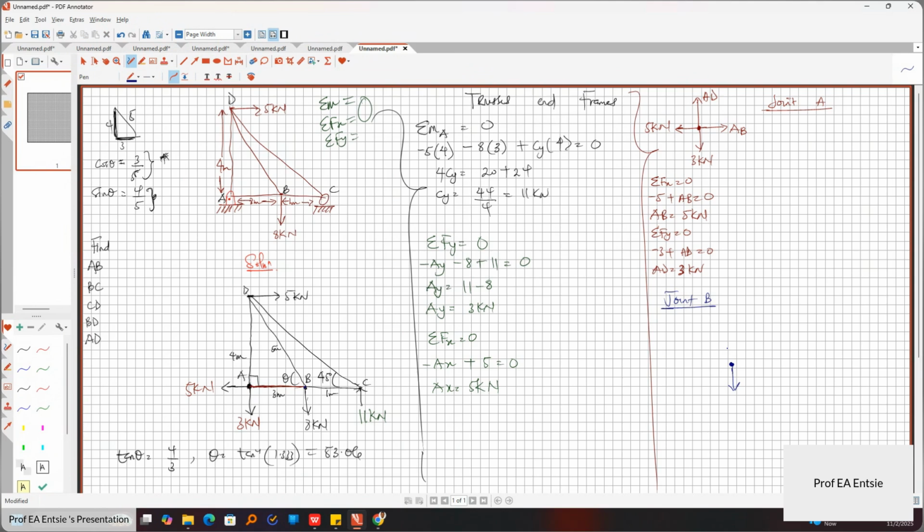This is where the argument is, and this is where you need to understand, so I'm taking my time. Just follow me. You see that at joint A, AB moved to the right. If AB goes to the right at joint B too, it means our joint is moving, or the whole truss system is moving to the right, which we don't want. The truss should remain stationary.